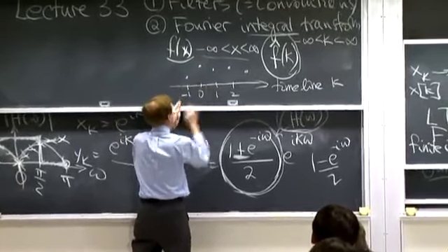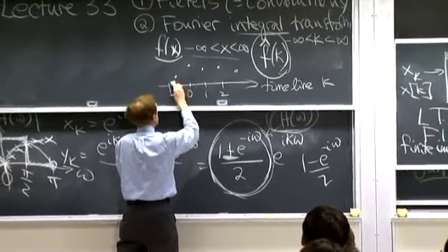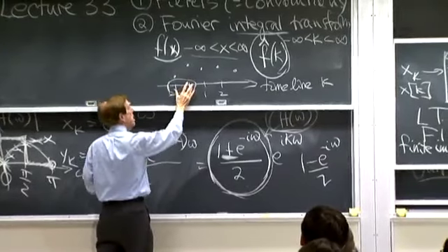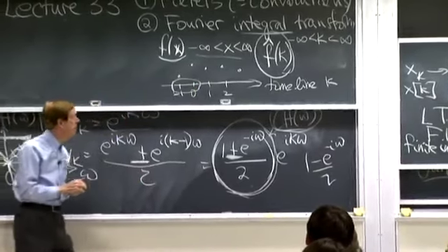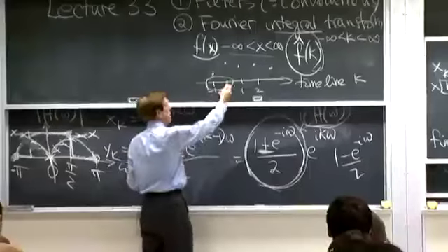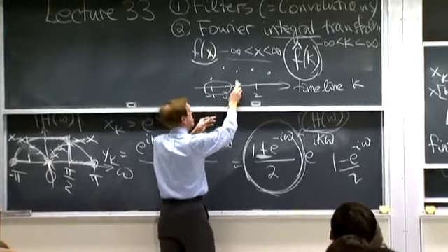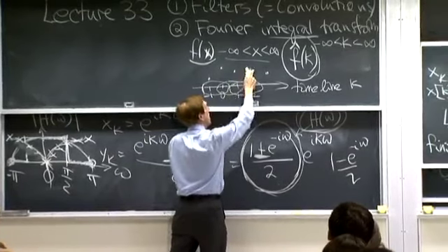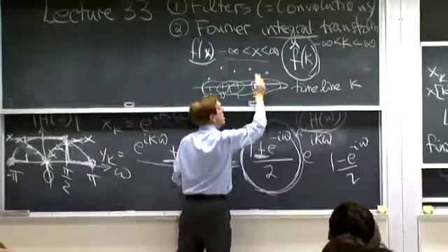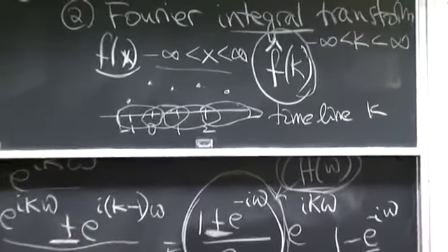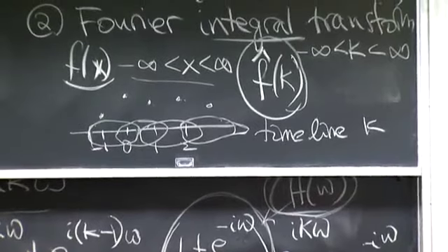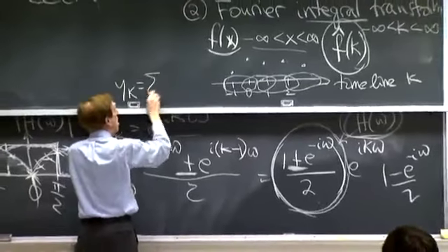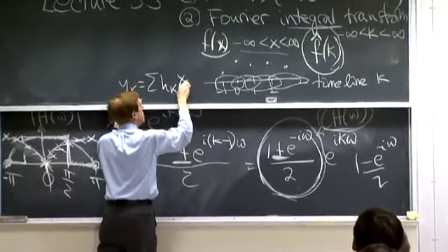When the window is there, it takes the average of those two. That gives me the new output. Now think of the window moving along, taking the average of these. Move the window along, take the average of these. Do you see? This is what a convolution is doing. This is a picture of my formula, the sum of h k times x L minus k.